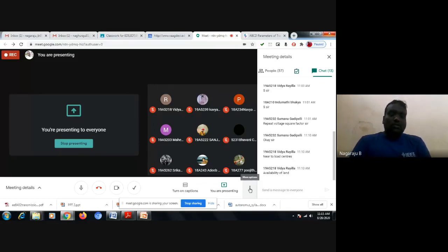And the location of the substation should provide enough space for the expansion of the substation in future. If loads are continuously increasing, you need to expand your substation. That is also required. The location selected for the construction of the substation should not be opposed by land use regulation, local ordinance, and neighbors. I told you in the first three clauses also.